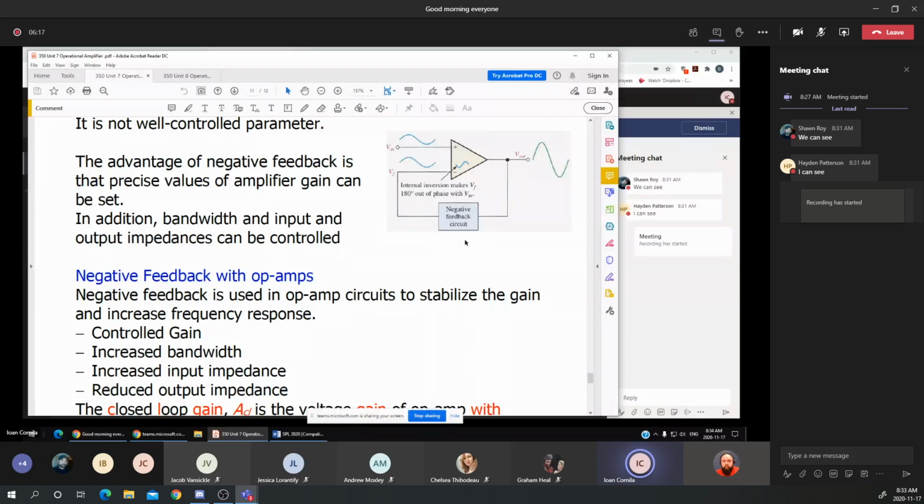Usually there are 2 resistors, or a resistor and a diode, or a resistor and a capacitor that will make the negative feedback circuit. We can look at a negative feedback circuit as a set of external devices that can be adjusted, that can be moved around the op-amp, that will do different functions and different circuits that may be used with an op-amp to have different applications.